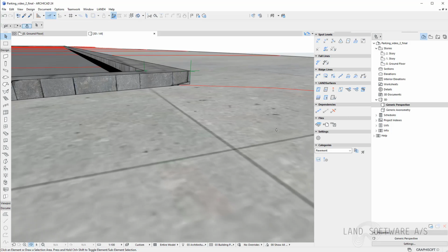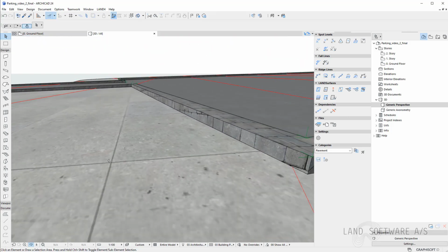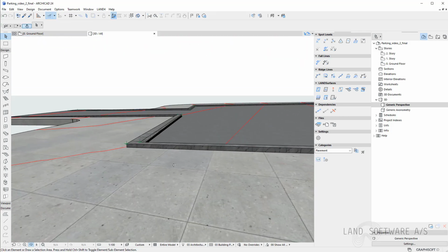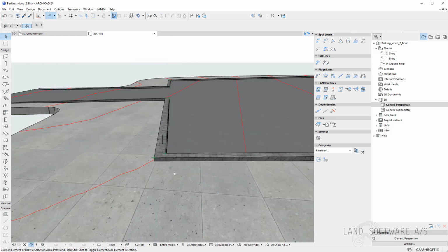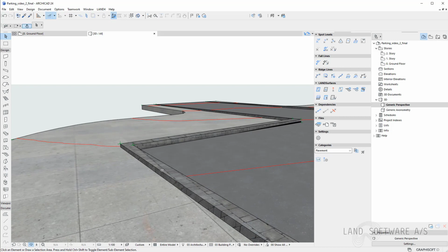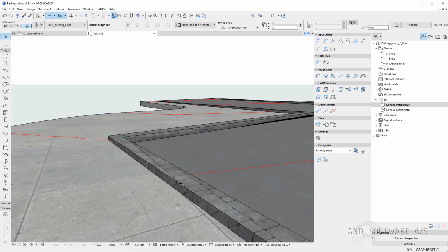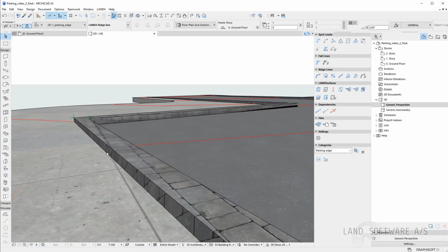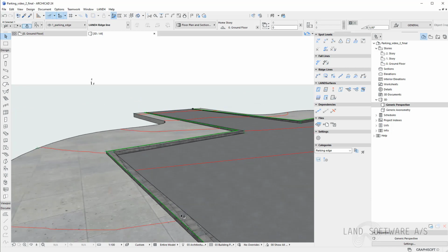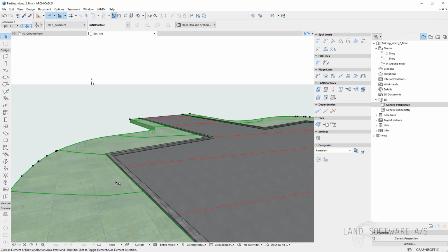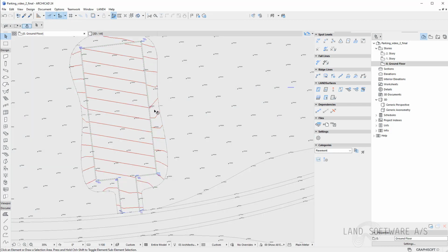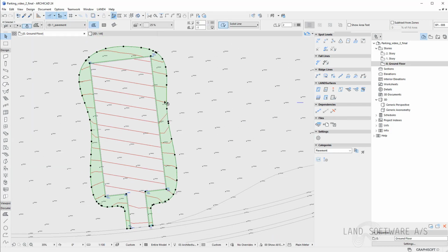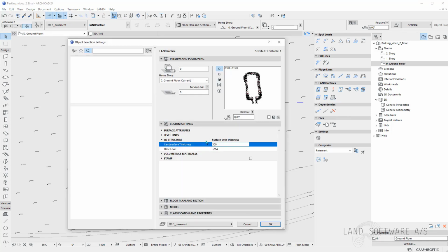When creating the pavement surface, I haven't used the ridge line from the pavement edge, from the outer boundary, which I can select. So this ridge line hasn't been included in the pavement surface. Therefore, the surface has been created using all spot levels all around.